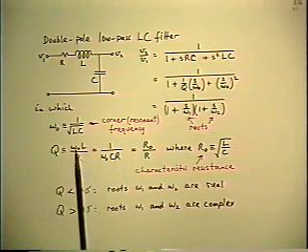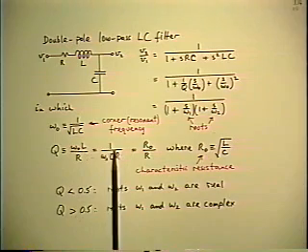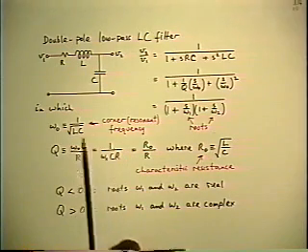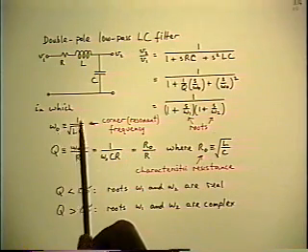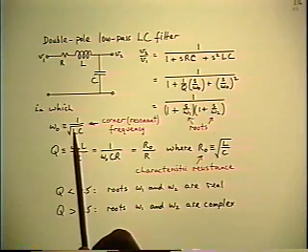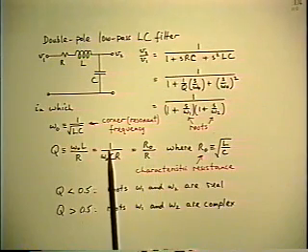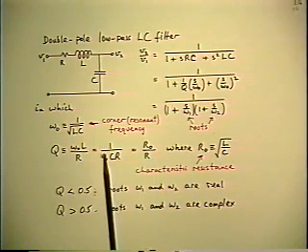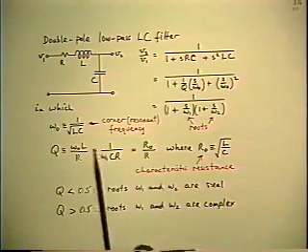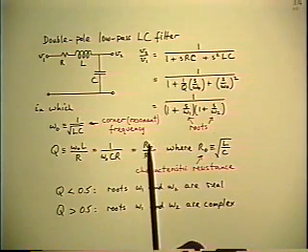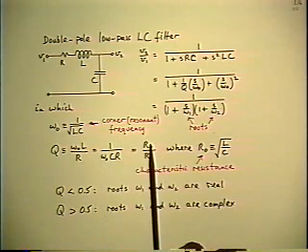That follows because the inductive reactance and the capacitive reactance are equal at the corner frequency by definition of the corner. The third way of writing it is simply identifying what those two equal reactances are. So you write them, either one of them, as simply R0, because they have the dimensions of resistance.